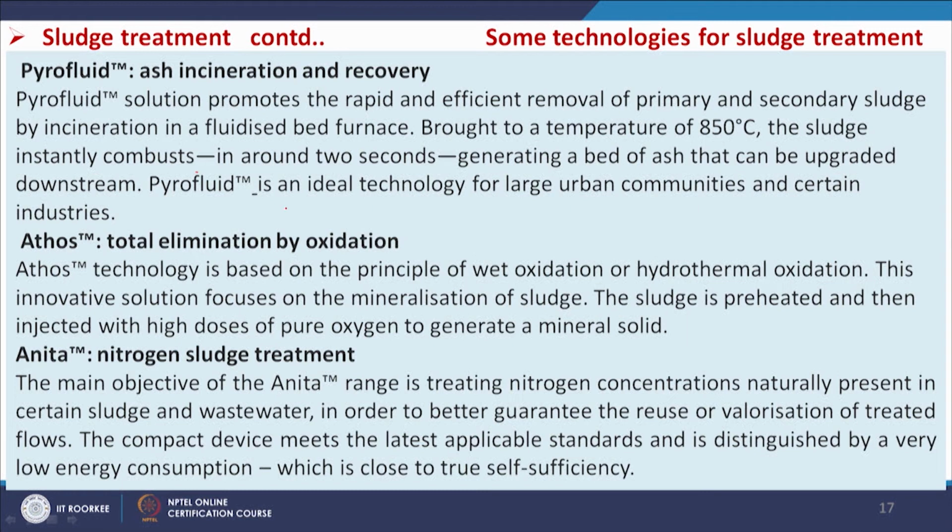Pyrofluid TM is an ideal technology for large urban communities and certain industries. And Athos TM, total elimination by oxidation. This technology is based on the principle of wet oxidation, or hydrothermal oxidation. This innovative solution focuses on the mineralization of sludge. The sludge is preheated and then injected with high doses of pure oxygen to generate a mineral solid.